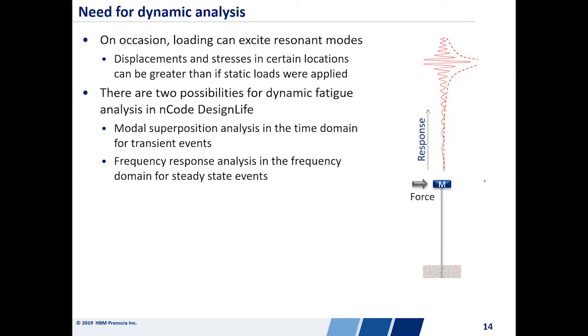Now, in nCode DesignLife, there are two possibilities for dynamic fatigue analysis. The first one is a modal superposition. It's going to be performed in the time domain, and it works well for transient events. The second one is the frequency response analysis. This one will be done in the frequency domain, and it works very well for steady state events. And that is, in fact, the focus of today's webinar.